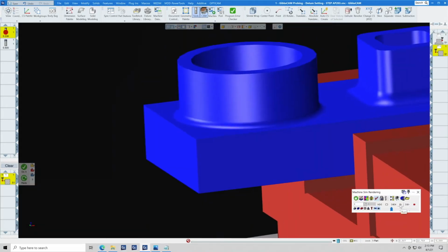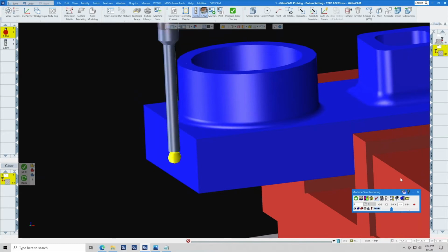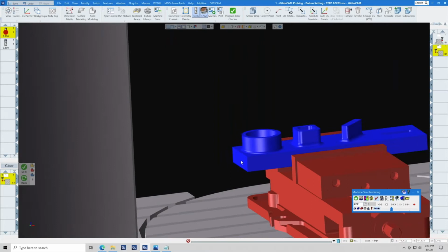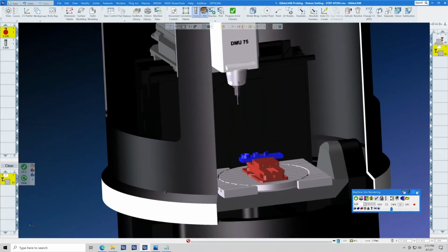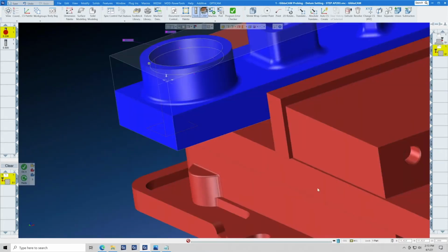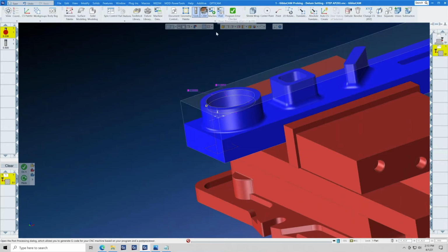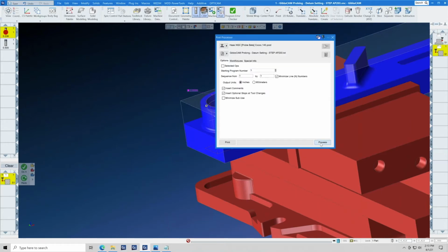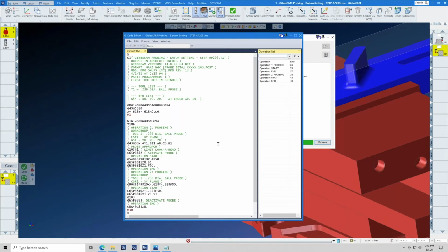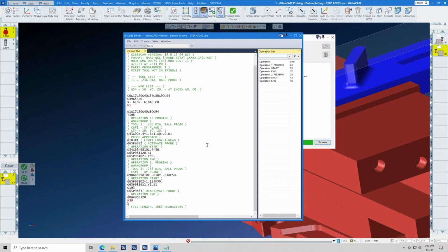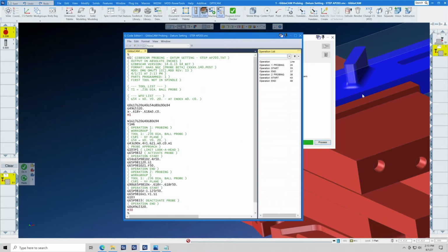Let's watch this very closely here. Here comes the Z, there's the X, and there's the Y. So this exercise is complete. And now it is stored in your machine, in your program forever. Whenever you go to run this program again out on the machine, you have the operator preset the 0 one time, and then every other time the probe goes in and does the work.